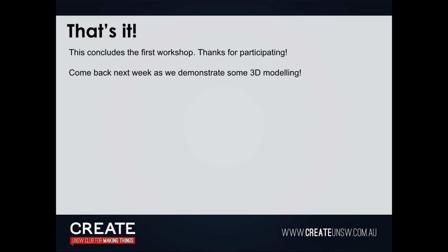From cut. Oh, come on. You have to do it on the 2D view, I think. You do project view. Yeah, do a projected view first. Yeah, we'll do a projected view. Yep. Oh yeah, that's right. With section, you actually have to do 2D side view. So we'll just do base view. Chuck that in there. We'll do that by 2, just so we can see. Oh, sorry. 2, right?